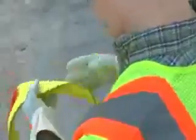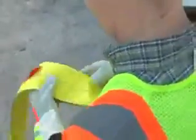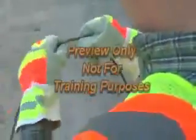Before any lift begins, the load must be properly rigged by a qualified rigger. One of the most important things to do before rigging is to inspect the sling and all fastenings and attachments for damage or defects. Damaged or defective slings should immediately be removed from use.